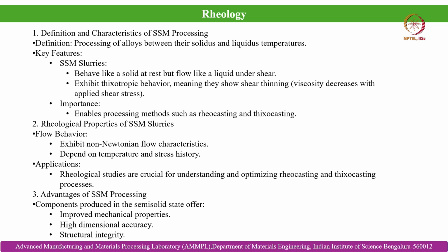As you may recall, when we discussed the casting solidification section of this course, we discussed that Rheo-casting is nothing but generating semi-solid slurry directly from liquid melt and then casting it in the semi-solid state, and thixo-casting is otherwise, where we generate semi-solid from solid ingots and then cast at that state to achieve the desired component geometry. So, this viscosity evolution of the slurry, that knowledge is of paramount importance to achieve success in both these semi-solid casting processes.